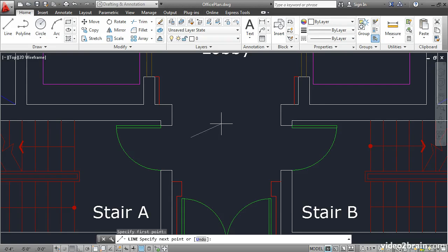Then go ahead and type in a value like this, 3 feet, using the apostrophe symbol next to the Enter key, and then type 6-1/2. What this means is 3 feet 6½ inches. The dash is necessary as a delimiter between the inches and the fractional inches. Without it, you'd either have 61 halves, or you'd have a space which would terminate this part of the command. Remember, the spacebar is equivalent to the Enter key. So the dash is necessary in imperial units when you're separating inches from fractions of an inch.